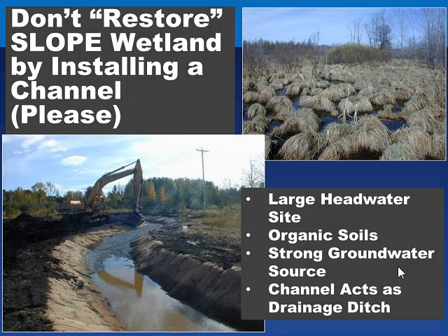But unfortunately, the net effect is going to be to lower the groundwater table from this channel, which is in effect a drainage ditch, and aerate the organic soil layer from the top of the bank down to the flow line of the channel, which over the next several decades will become aerated, oxidize, and completely cause subsidence in the land surface, plus the loss of thousands of tons of organic material to the atmosphere.